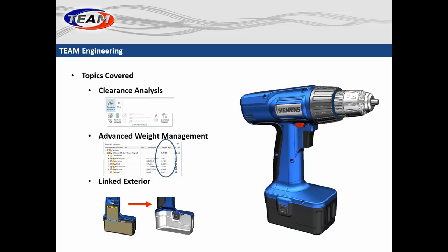We'll also be having a look at advanced weight management. There are some nice tools in here where we can get a real quick and easy look at what the total mass of one of our assemblies is. Really important for mass critical, weight critical assemblies.